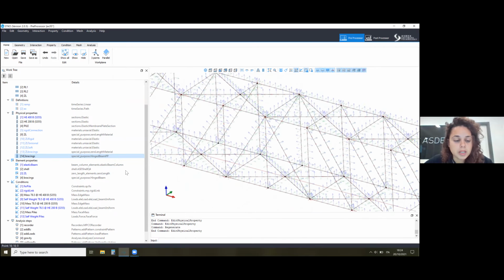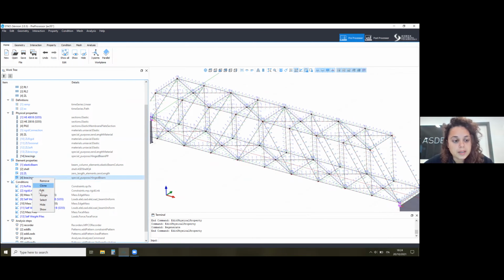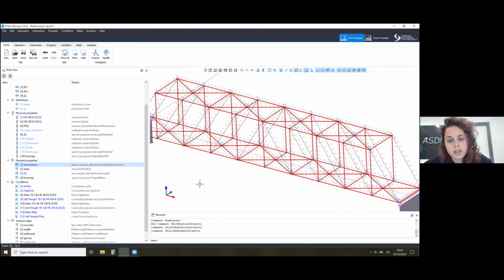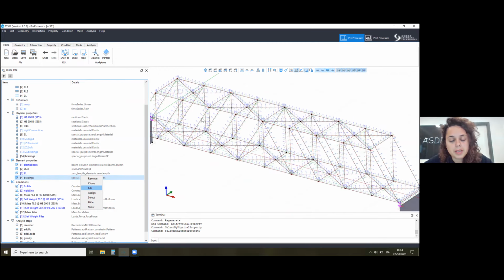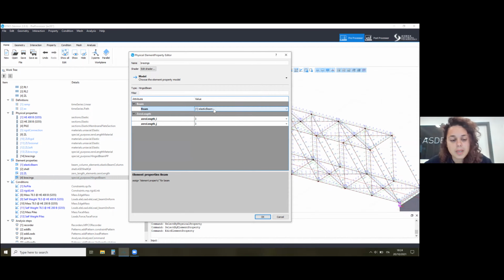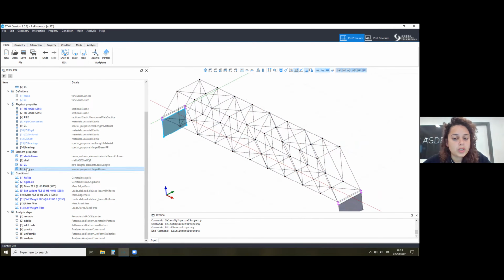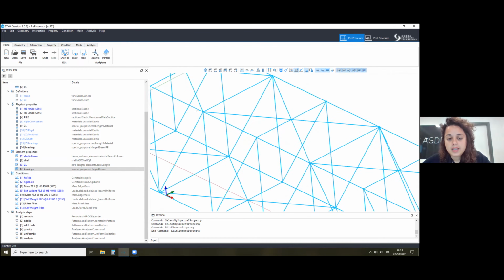The only difference between this model and the one before is that you cannot just apply this physical property and then keep the elastic beam column. Otherwise, your model will not run. You will need to apply a specific inch beam element referencing another in the same case. So you will have to have created the elastic beam column or force beam column, displacement beam column, whatever, and also a zero length element. We already had these because we applied that to the interaction, so we were lucky. Like this, we have the possibility to simulate the absence of connections in terms of rotation.